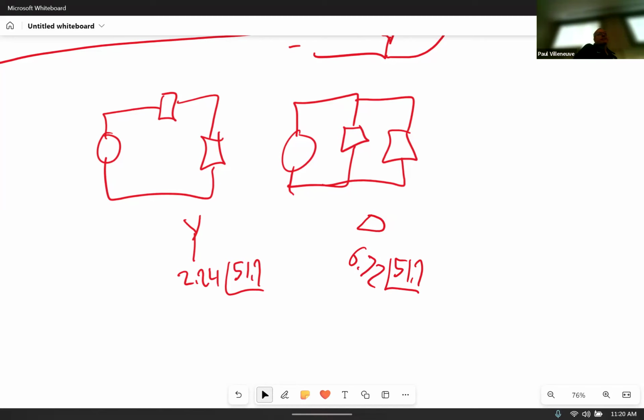So you convert one delta to Y, or the Y to delta, either one would work. And then since they are both in parallel, you use the parallel formula. Yep, 1 over Z1 plus 1 over Z2, invert that. It's just the single resistors. The single resistor, yep. Because again, when I talk about a resistor in a three-phase system, I don't have one resistor.